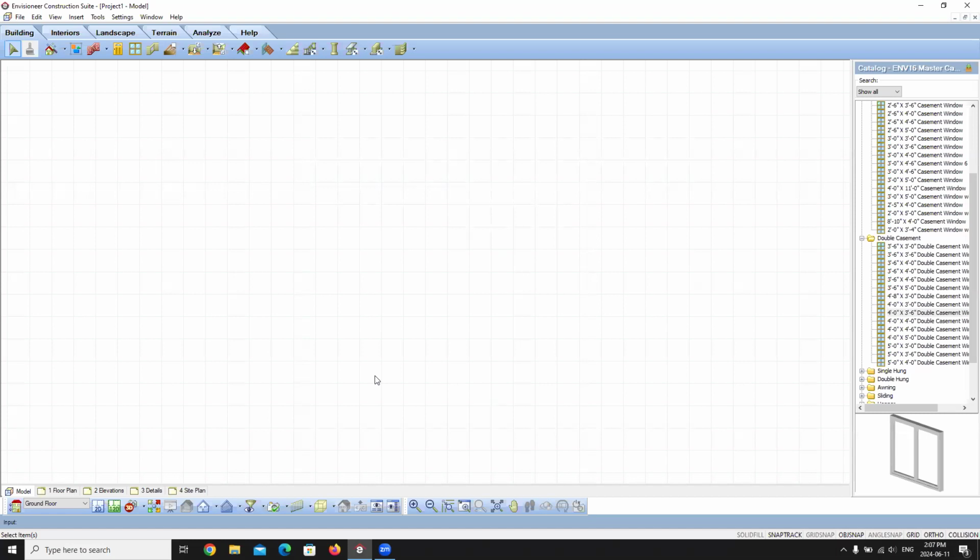working drawing sheets. But in the document that I'm going to send you, there's going to be a list of some different view scales that you can use for different elements that you want to insert, or different views of your floor plan that you want to insert. Typically, anything that is going to be in an elevation view, you can have that insert at 1/8 of an inch is equal to a foot.